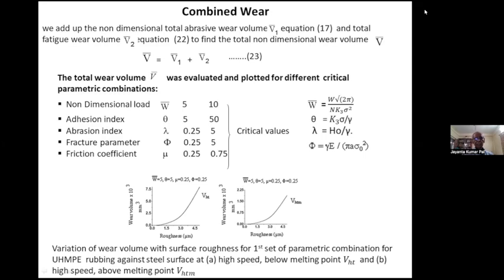So these two figures are quite clear, and they demonstrate quite clearly that for small roughness, total wear for polymer is small, and at high roughness, it is fairly high. So that gives a very useful industrial tip: not to use very rough surface which would be rubbing against polymer.